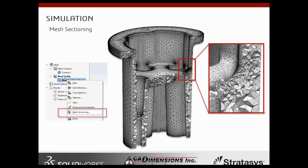Now this is fairly important when you're dealing with parts with varying thicknesses, and you're using some global mesh setting there, and you're not using any type of initial mesh initially. You could create your global mesh and create a mesh sectioning, and then select certain edges or faces to create your initial mesh. So this will also help you to create a better mesh as you're creating or refining your meshing.